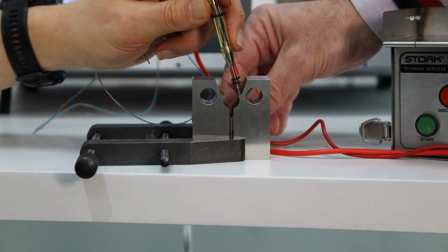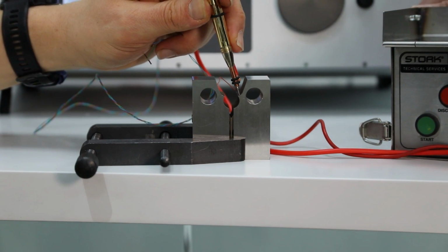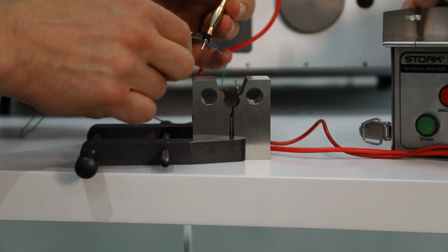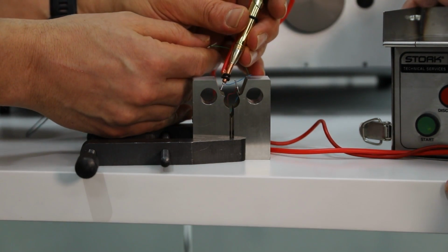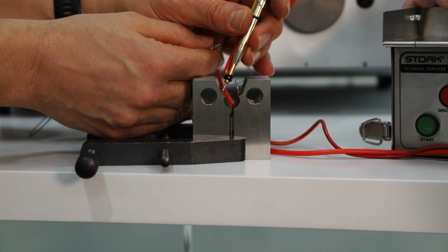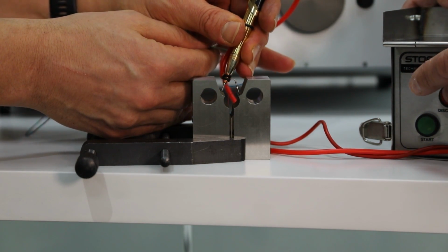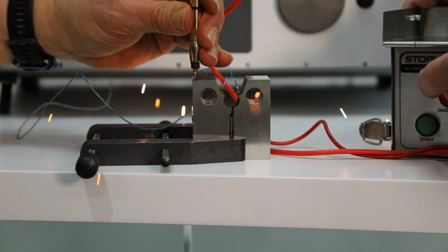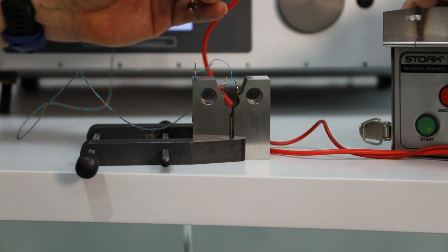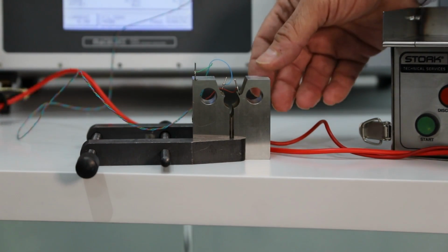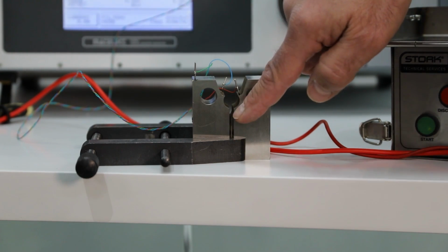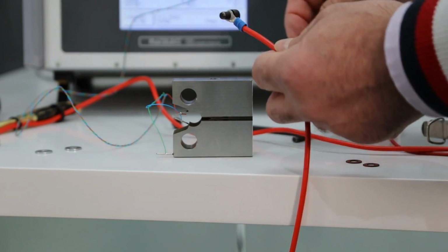So this is just the thermocouple welder with a specially adapted head, and we're putting a pin on which is being pre-wired with the voltage wire. So that's a voltage connection, and then the next one goes across diametrically opposed on the other side. That gives you the average DCPD. These are positions recommended by ASTM, and then the reference goes in there. There's 3 connections, but actually there's, if you like, two measurements. One is common to the other one.